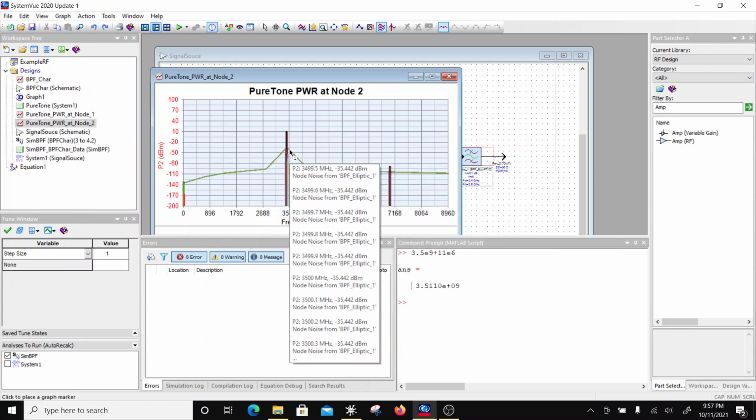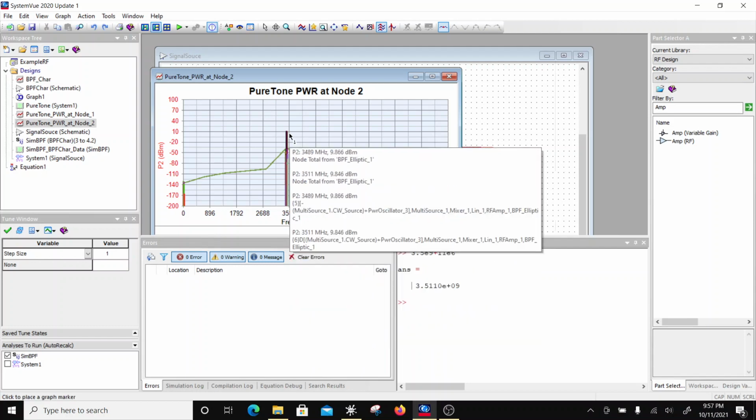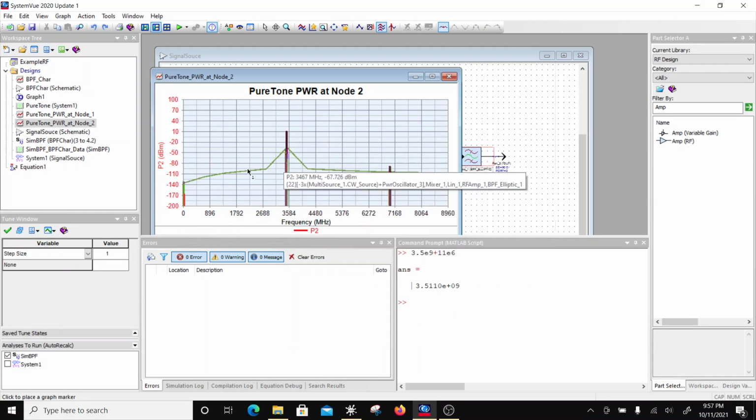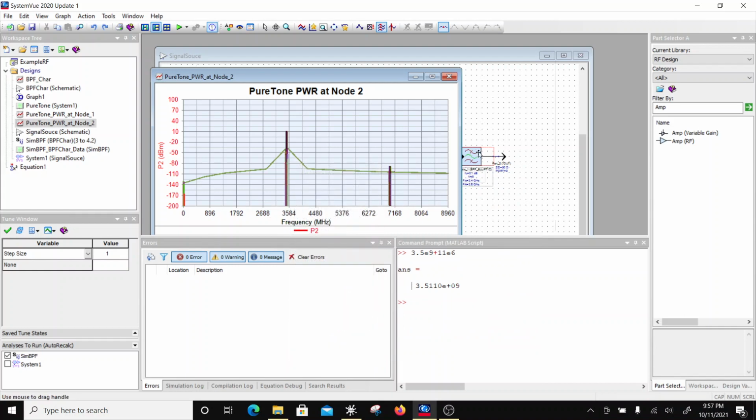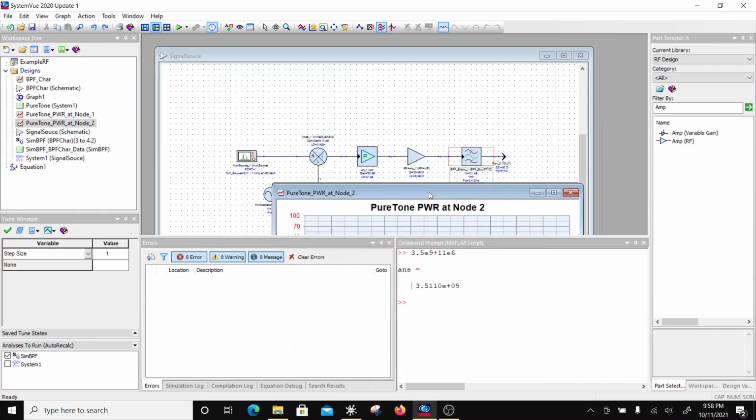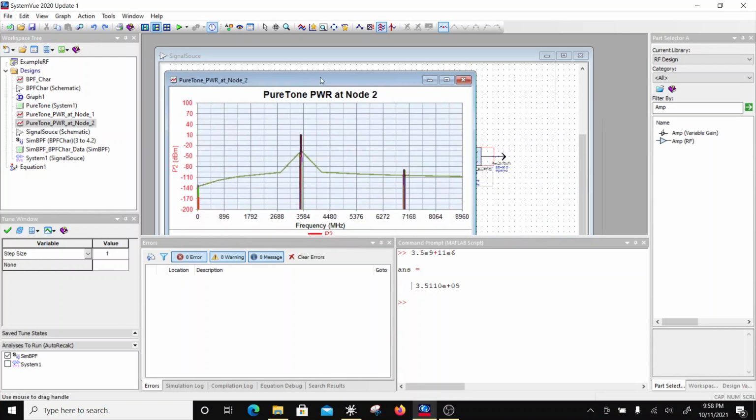This is still 45, minus 35 here. This is still 45 below. But if there is a non-linearity in the system, this noise should not fold back over here. So that's the function of this image reject filter here in terms of noise. Of course, when you do heterodyne, you will understand what that image reject filter is doing.